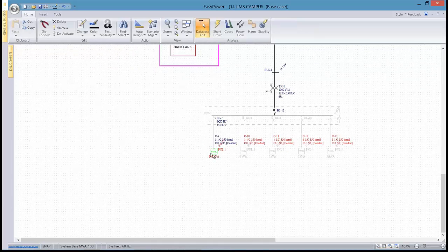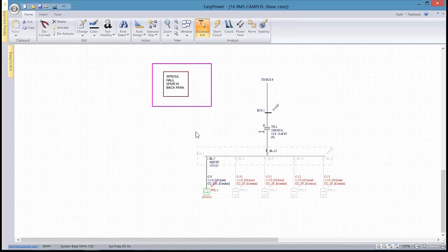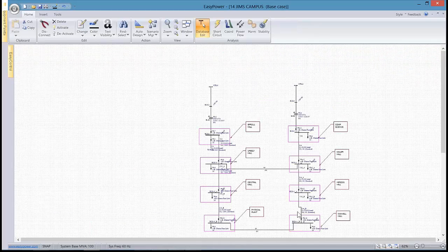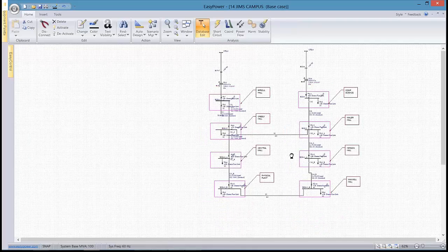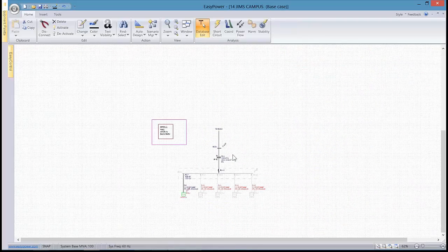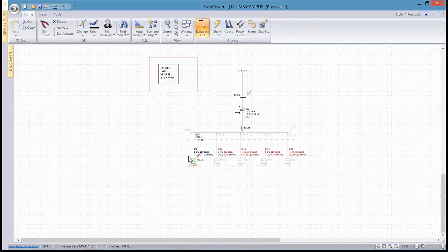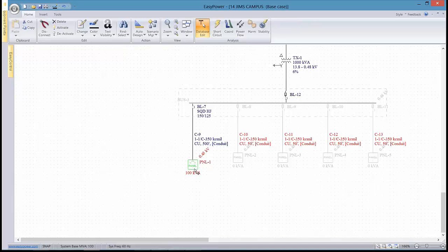So let's go ahead and open that up. Okay, but this actually is the point I was driving at. At this point, I've isolated my system, and the only thing that's being included in the short circuit analysis as I change the focus is that ring above, and then this one feeder leg that goes down to this panel. Now what I want to do is methodically go through and characterize the data that's required for this panel until I understand specifically how to produce arc flash labels, and consequently once I've got that level of detail included, then,